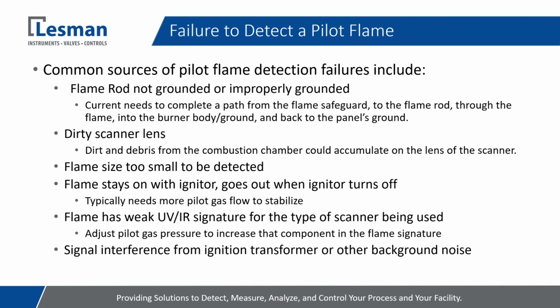Flame has a weak UV signature, right? So again, I've seen it before where you've got a very, very pale blue flame. It may not be producing the strongest UV signature, and so you may need to make some adjustments just to bump that up.